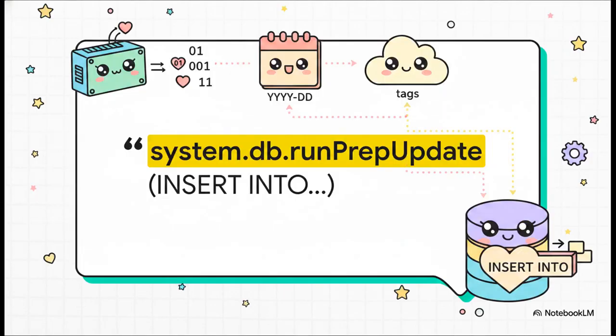So the crucial point is this. Here is the big payoff. Once we've read our tags and formatted our dates, we execute system.db.runPrepUpdate. This incredibly powerful command pushes all that gathered data directly into our SQL database using an insert into query. Just like that, your PLC event has been perfectly captured, formatted, and permanently recorded in a structured database table.